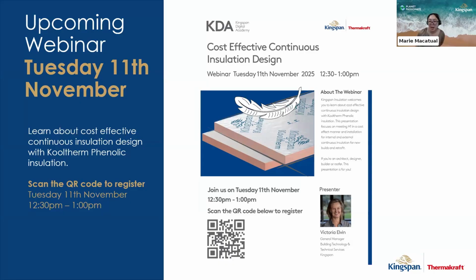Can height safety anchors be used over PIR warm roof? Absolutely, but I would think that they would need to be designed through to the structure for the height safety system. Again, that would be a proprietary system detail. It would depend exactly on what type of system is being installed, but that conversation would be had with the proprietary system partner and the chosen height safety partner to ensure securement and performance of their system. But yes, I would think that would be very possible.